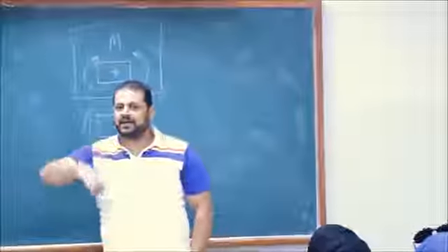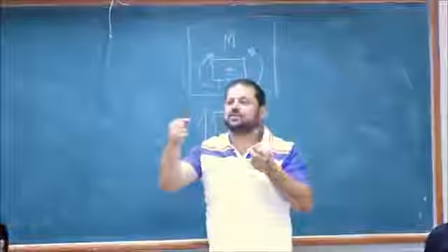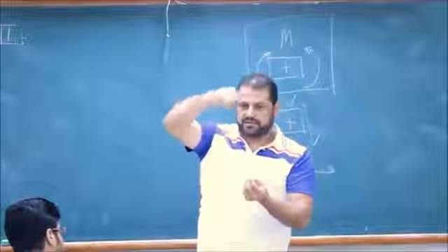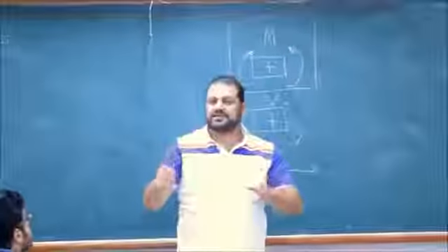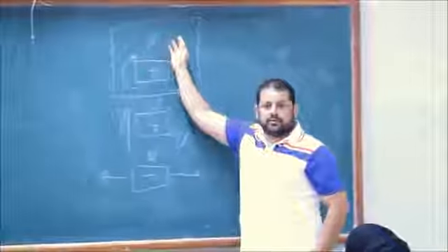If we are designing steel members, the member in compression may experience buckling. So the design for compression and for tension, even for the same load, meaning you have the same force acting on a steel member, whether this force is tension or compression, is completely different. Completely a different design for the same force. So it's very important to know.